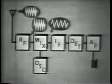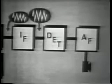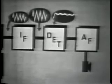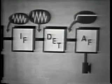But what happens at the detector? You recall what a detector does? It rectifies and filters the IF signal and detects the amplitude variations. But a single sideband signal, modulated with a constant tone, would have constant amplitude. The detector would rectify it, filter it, and out would come pure DC. No intelligence. So what must be done?